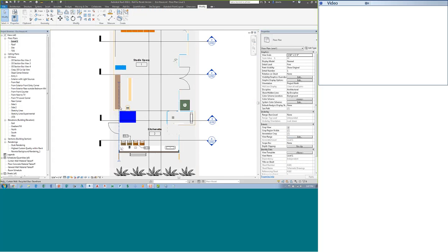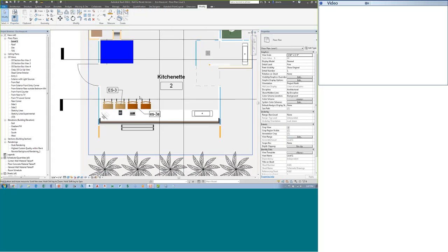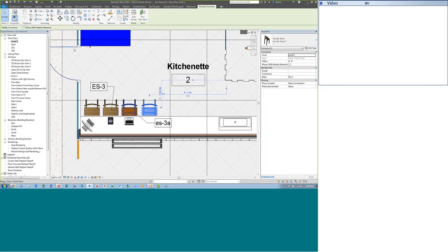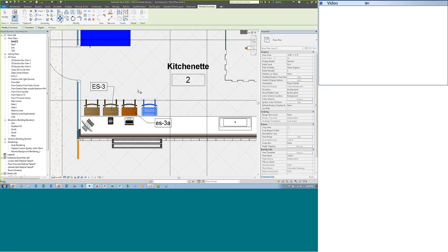Now, you can, however, just select the entity first. So if I select the entity first and then I use the move command, it goes directly into the move command without requesting that I hit Enter or spacebar, and it basically saves another click. And so then I can click and just move where I want, and it's done. And that's another way to move.